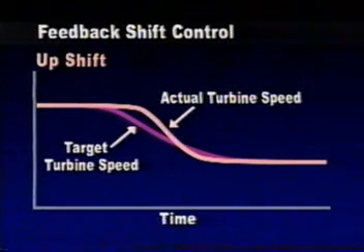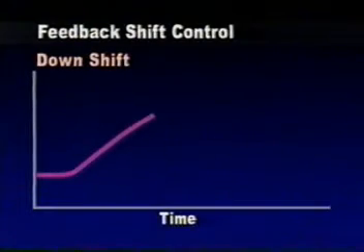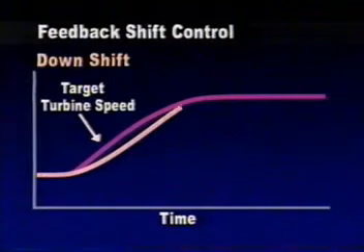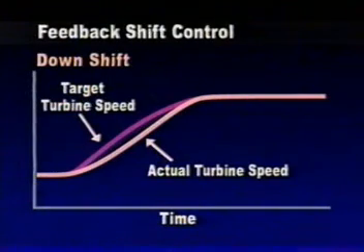Of course, the shifting feel is fairly improved. Even when the output performance is changed due to the old engine or automatic transaxle, stable shift is enhanced by the automatic duty ratio compensation of solenoid valve.